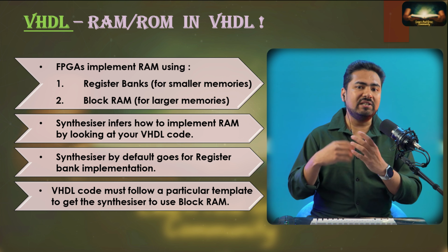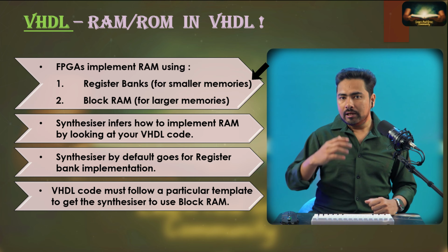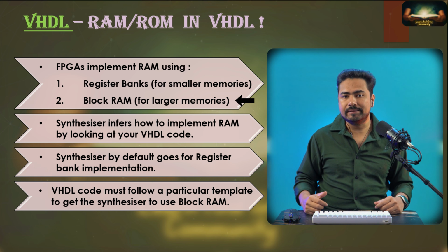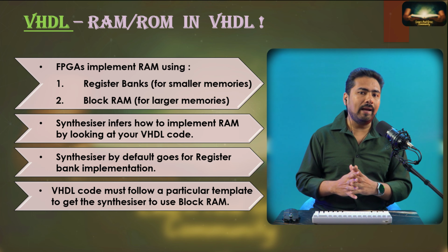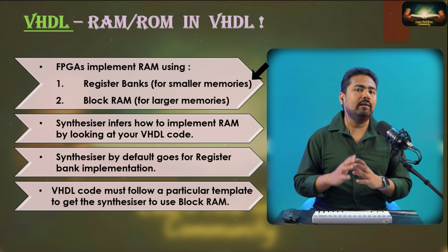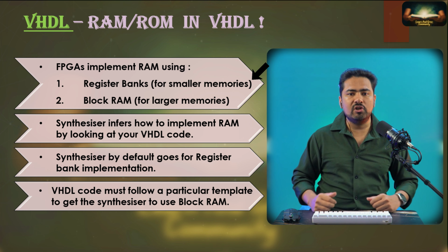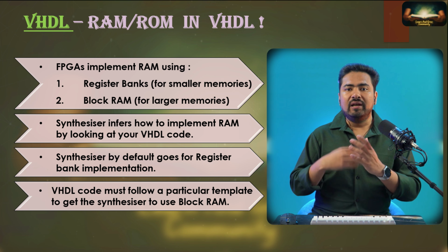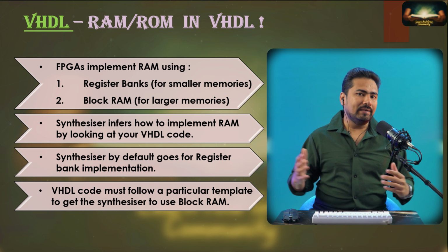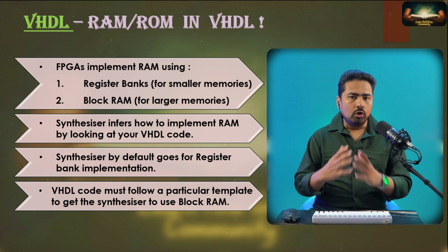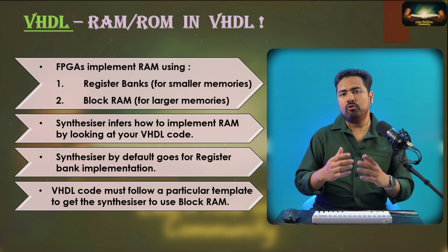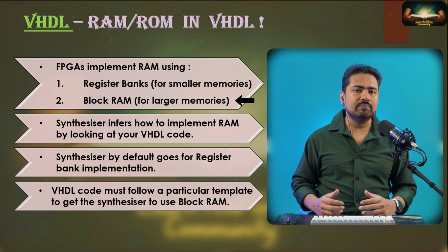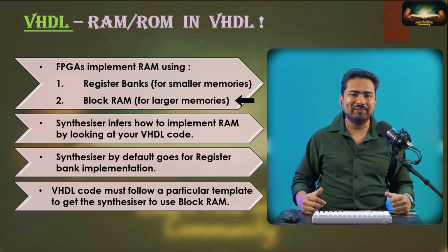However, there are some disadvantages of register banks, especially when you need larger memory elements for your designs. If you only rely on the register banks, they can quickly exhaust the FPGA flip-flops. And it is not good because it will limit your ability to implement bigger systems that need a lot of resources and elements from your FPGA. So we need a different way in such cases for more data storage.